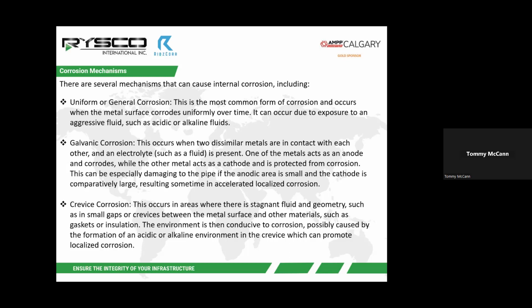The environment can be very conducive to corrosion. There's potential for an acidic or an alkaline environment in the crevice, which can then also promote localized corrosion. Not, in my experience, generally considered the higher risk of the mechanisms, but one that definitely needs to be monitored and measured.